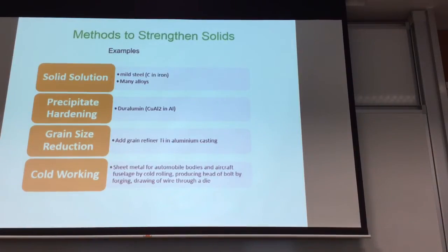Yes? Now imagine next, we have another set of rollers. You know you cannot just sheet it once. So you need another set of rollers. What happens here? You reduce the thickness again. So basically what you're doing is, you go back to your stress strain curve, what do you do? You add more stress, but the curve starts from where? A or B? So the curve starts from B.